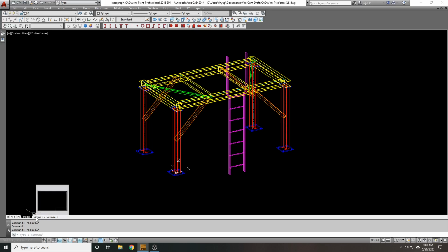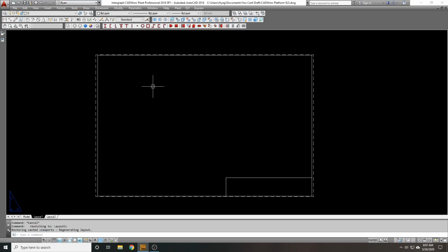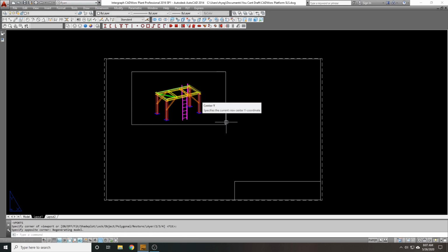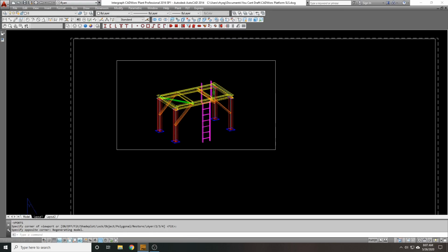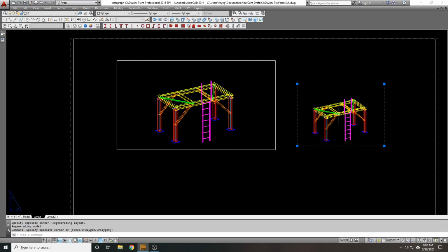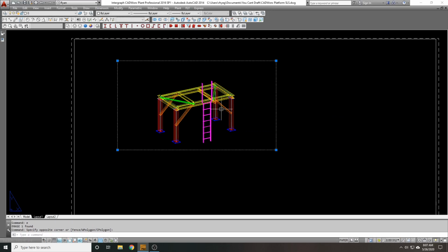So what I'm going to do first is go into my layout and create a new viewport. However you get to yours, mine is an alias for Lispertine, but you can just type in viewports. I can't even spell right. Viewports, and just choose single, and that'll get you there as well, or use the viewport toolbar. All right, so now I've got my viewport created. I'm going to want to pick my view. So we're going to do plan view, then we'll do some elevation views.